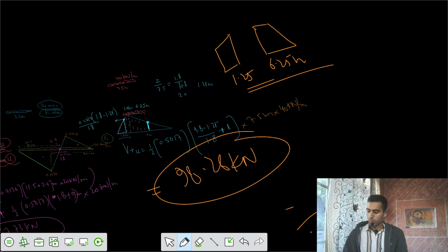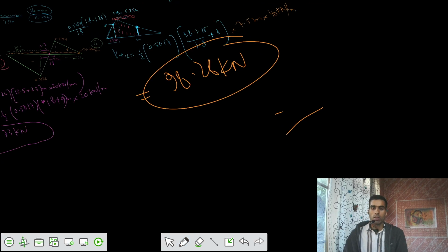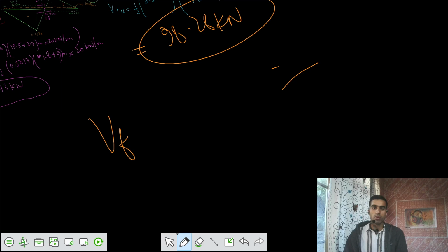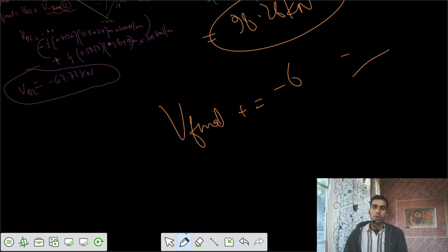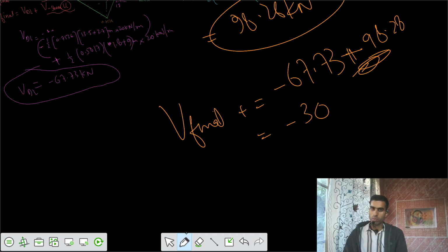So what is the V final because of positive? V final positive: initially we had dead load minus 67.63, and I would add that positive 98.28. So minus 67.63 plus 98.28 gives positive 30.53. This is a positive value that you got.